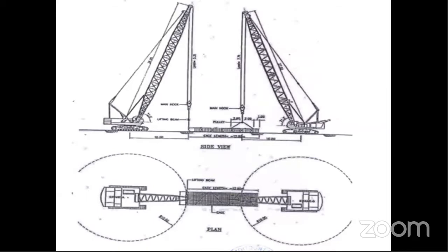All these things, like dowel bars for the slab, should be provided at the time of fabrication itself, because later, at the time of slab casting and slab reinforcement, it will become extra work. If we provide the dowel bars now, it will be easy to bend and join those dowels to continue the reinforcement.